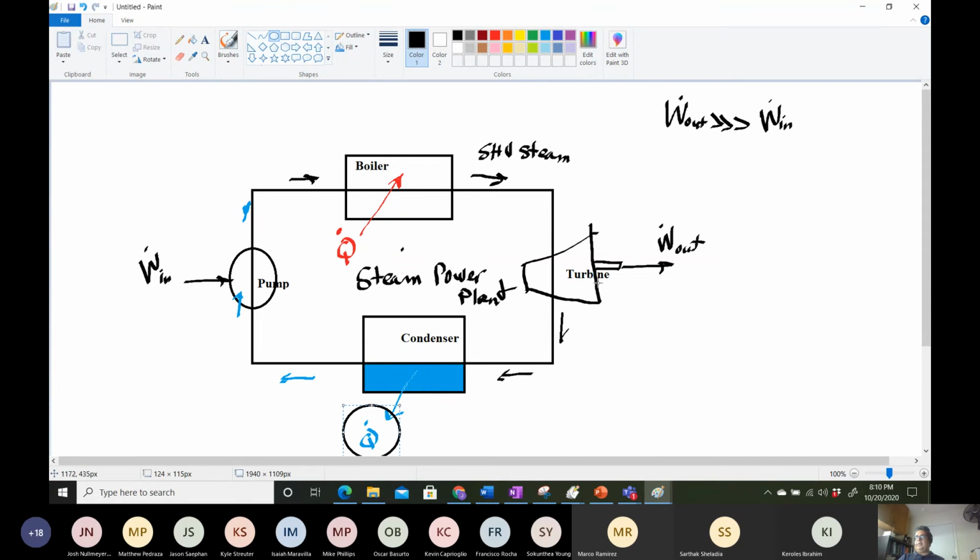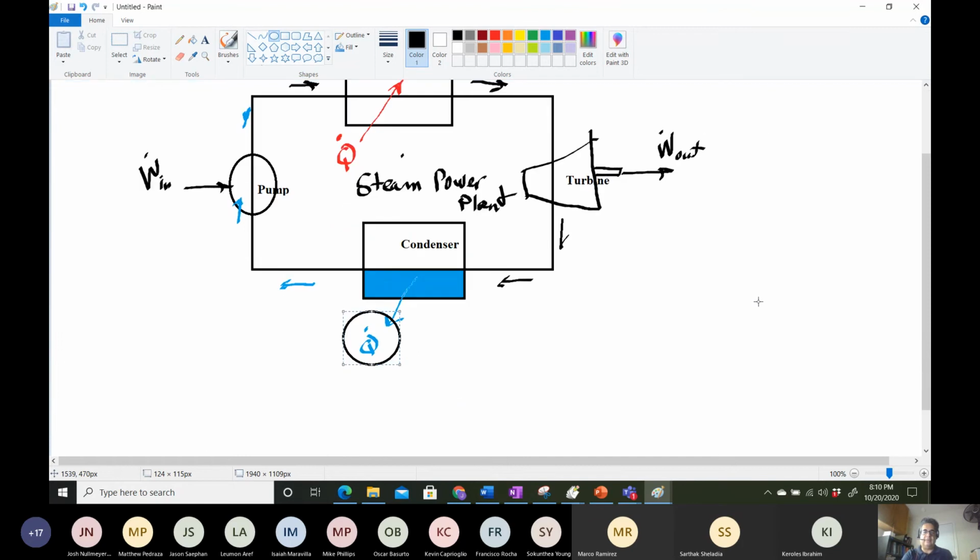For the temperatures that we operate in, the efficiency of the turbine is usually no greater than 40%, right? The second law of thermodynamics tells us that you can never get anything better than about a 40% efficient turbine. Maybe 50 if you found maglev bearings or did something weird. But you'll never. We have to throw energy away. It's the second law of thermodynamics.